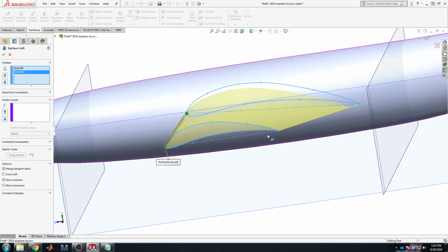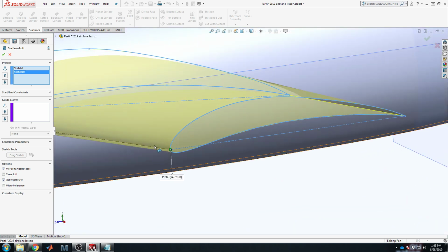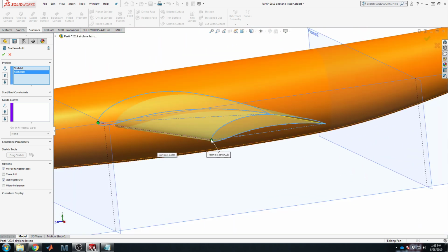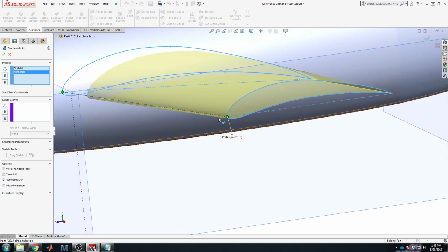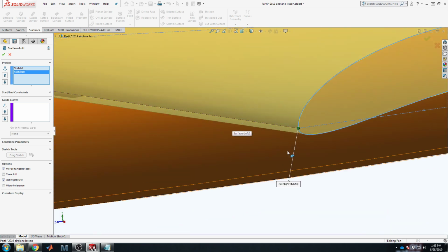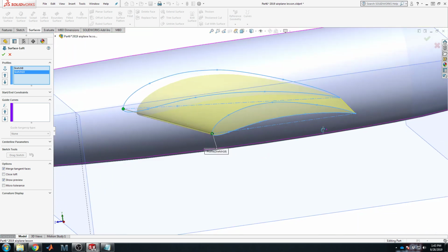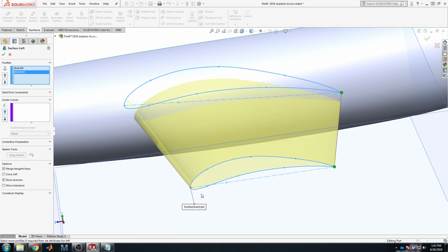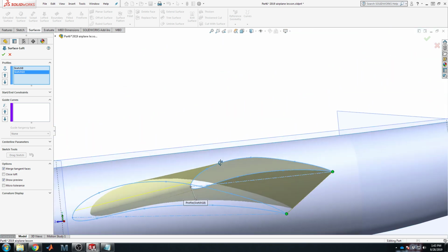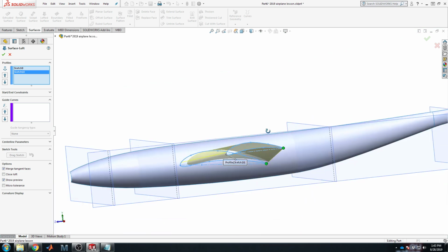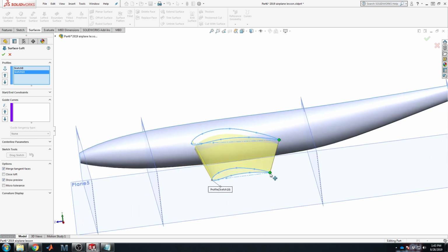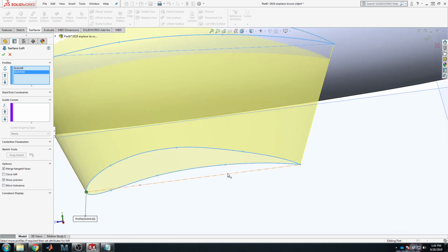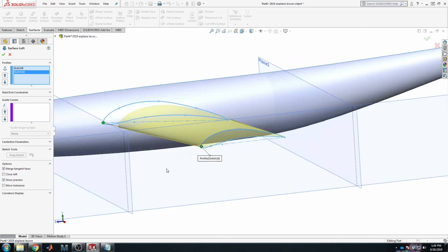Yes, it does. It's massively convenient to have that inbuilt split in the surface exactly for top and bottom. So the difference I'm talking about is now you see that yellow line that's underneath the black line going across the exact leading edge. With the other choice of closing points, it wasn't exactly at the leading edge. See, it crept up the top surface a little bit. That means that the bottom surface plus the entire leading edge would be one surfaced section, and the top was something different. Because by placing it at the rear side of the airfoil, you're allowing SolidWorks to make its own choice on where to place that. Or if you set these closing points at the front, the exact leading edge, then now these divisions of surfacing make much more sense, and you're good to go.